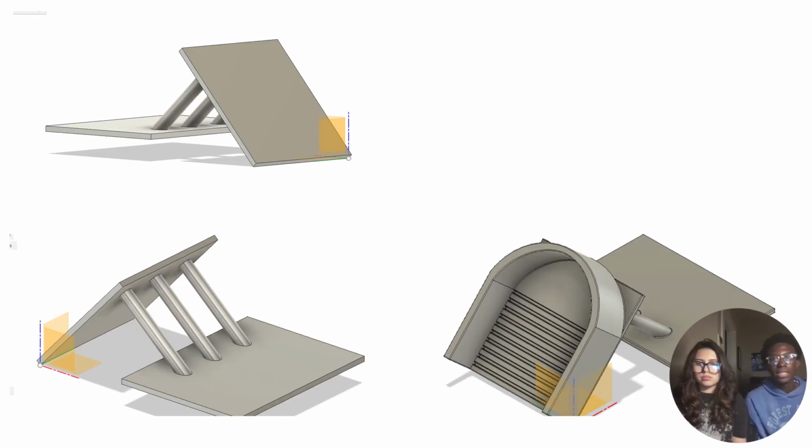So we redesigned the entire top mechanism into a single 3D printed piece. This combined both the pressure applier and the foot pedal itself. While before we had a 3D printed foot pedal connecting to some form of base, connecting it to the poles, which would be wooden skewers or wooden poles, which would then connect to some base attached to the whole thing being attached to a binder clip, and then the base presses down on the piezoelectric discs. We combined the entire system into one 3D printed piece.